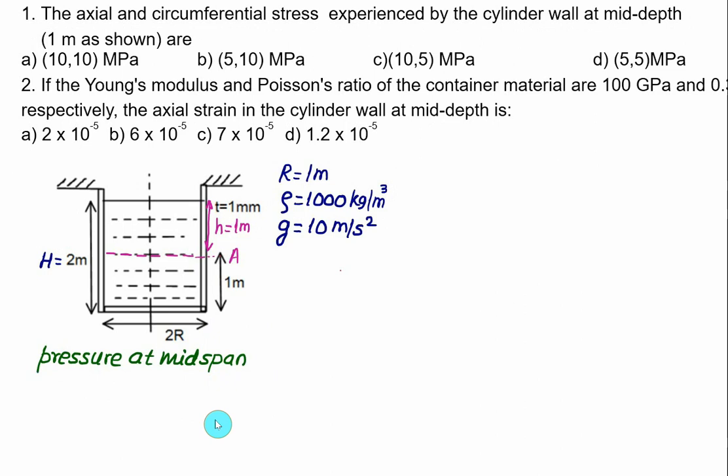So first we calculate what is the pressure at point A. That will be due to the column H. So we have pressure at point A will be the product of rho multiplied by g multiplied by depth equal to H, that is up to point A. Density you have to use is equal to 1000. Acceleration of gravity you have to use as 10. Depth is equal to 1. This answer will be Pascal, and this value represents the gauge pressure.